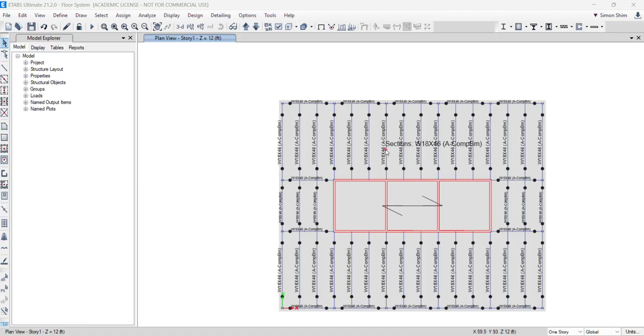So, where we are, we just built a 3D model of one typical floor framing. This floor framing is relatively simple. I start out with the regular grid system, but in reality, it's more complex. It depends on the building geometry, but you can apply the same method. Sometimes you may end up drawing a different way, maybe using the AutoCAD background DXF and putting it as a background, and you can draw the columns and beams, something like that.